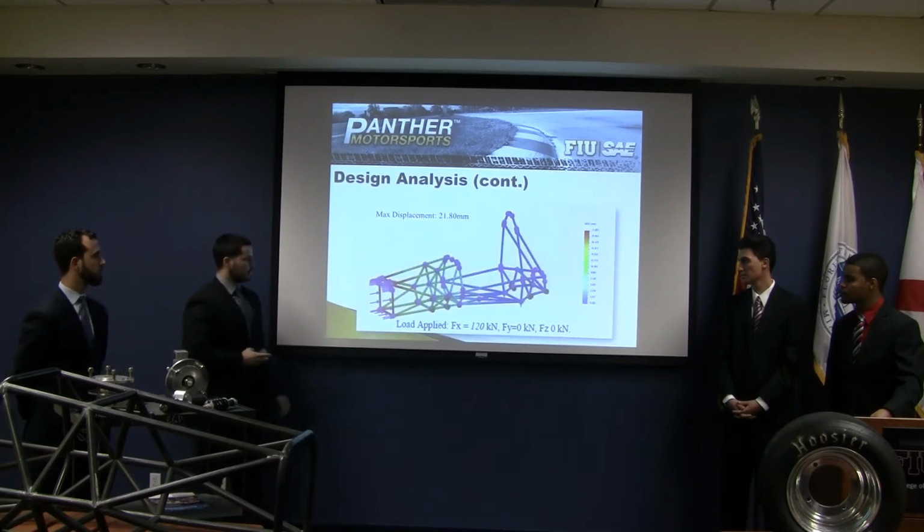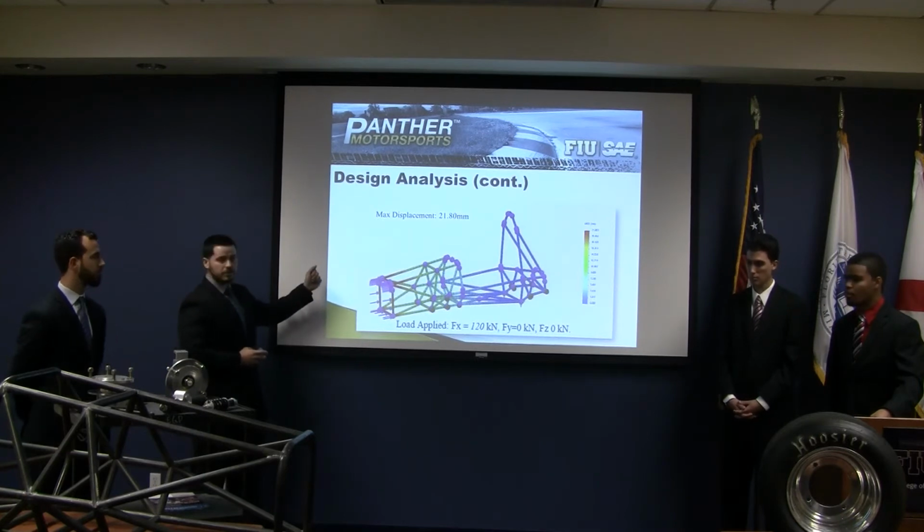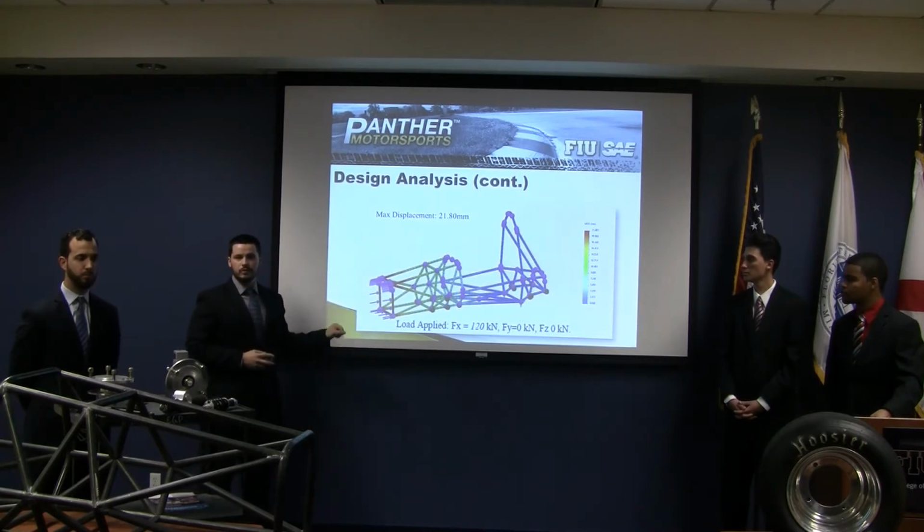As we see here, we've simulated a front impact scenario with these loads and resulted in a maximum displacement of 21.8 millimeters. Something I would like to mention is that forward of the front bulkhead, there will be an impact attenuator which will mitigate some of these loads.